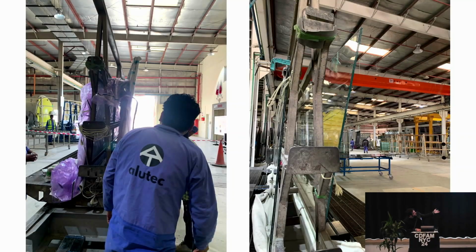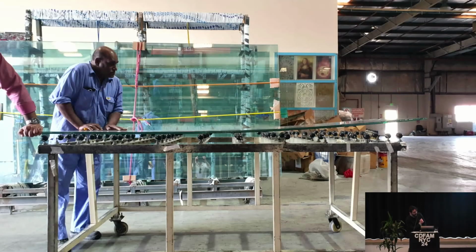By the way, the way this is fabricated is that the glass is actually held in its final shape. You put it on a rack, you twist it out of place. That thing goes into an autoclave, which bonds the two pieces of glass together using an interlayer, like an adhesive sheet, basically. So that's why at the end it doesn't need to be braced. The interlayer in the middle has returned back to room temperature and nominal stiffness, and that's what's holding these panels in place like this.